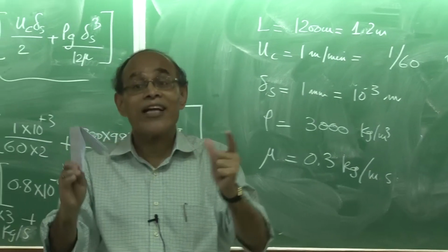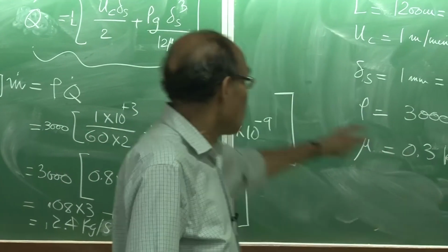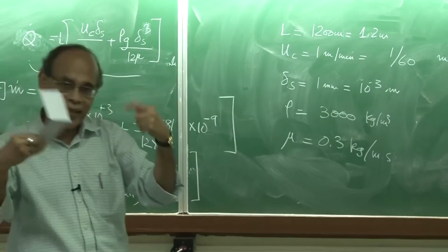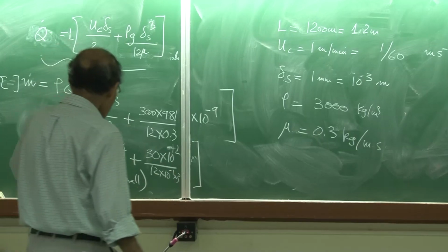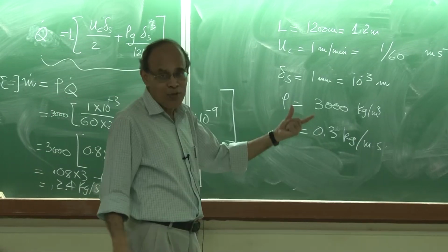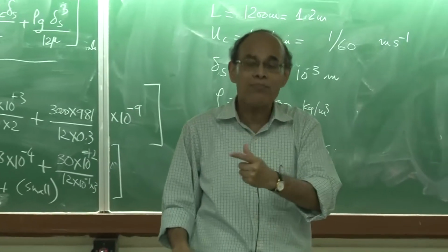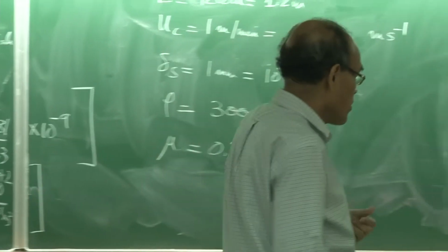So, you accept that there is a procedure called shell momentum balance. If one does a shell momentum balance, one will be able to arrive at a mathematical expression which one can solve, and then one can find the velocity field, the mass flow rate, the average velocity, and so on and so forth. This is just the beginning, and then we can proceed to develop more advanced frameworks and perform the analysis. That will be discussed in the next class.